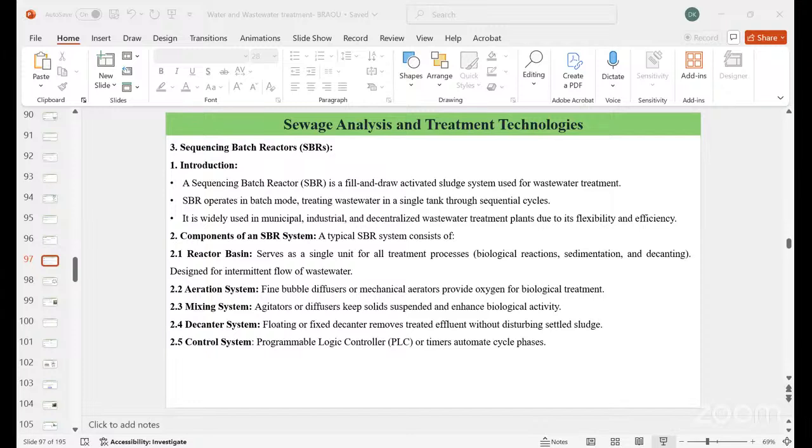As we look into the picture here, there is a chlorine injector where the water is stored and then pumped into the storage tank. In between there will be a chlorine injector, where the chlorine can be injected, and that is how the water can be disinfected. Then we can also filter the sediments present near the tap, and obtain clear water. Excess chlorine can always have a potential for carcinogenic properties, so there should not be excess chlorine levels in the water.